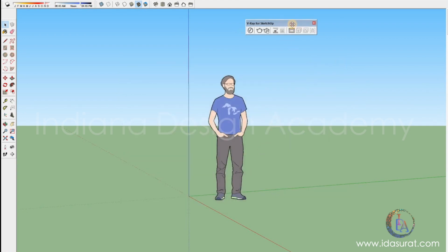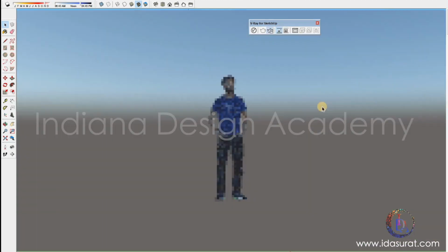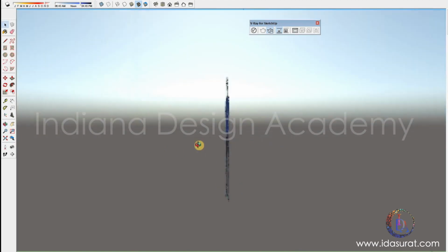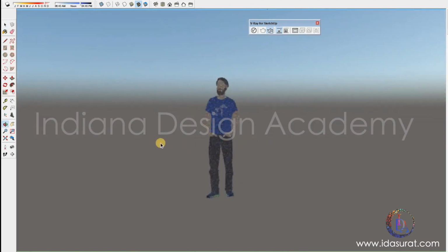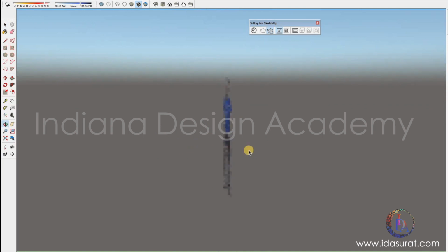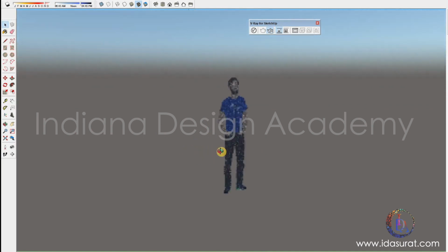Okay, now in this toolbar, after that we have viewport render. Now viewport means what you see right now on the screen. I am moving the cursor. With the viewport, what I see of SketchUp, whenever I initiate this viewport render, it will render in this viewport, not in any frame buffer. So whenever I move, you can see on the screen, it is not showing me in any frame buffer, it is showing me in the whole screen. So this is the basic difference between viewport and interactive.